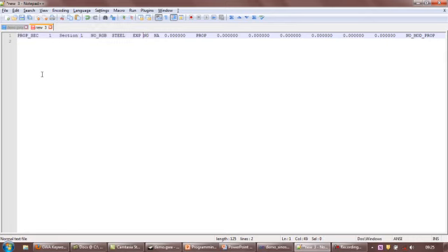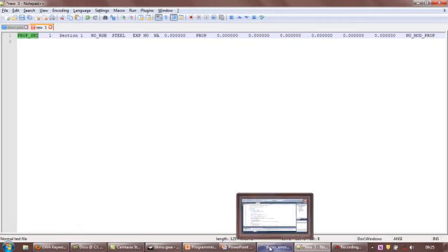So the string that we have here is actually in the GWA format. If I copied a section property and look at the first keyword in this string, it gives me the actual GWA keyword. PROP_SEC is the keyword for the section property entity.